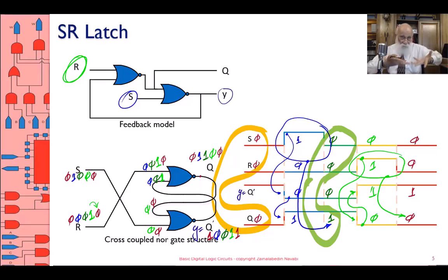If I just turn the circuit around, Q becomes Q bar, Q bar becomes Q, S becomes R, R becomes S. So it doesn't really make any difference which one you call your output, which one you call your feedback, or both of them are your outputs. If you like the Q output, or if you want the active low output, use Q bar. Okay? What I've shown is my circuit has memory, and that's important.